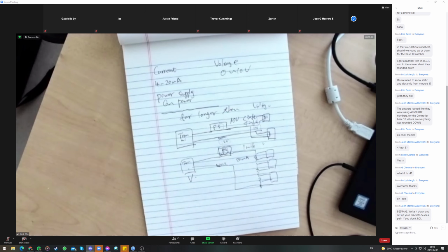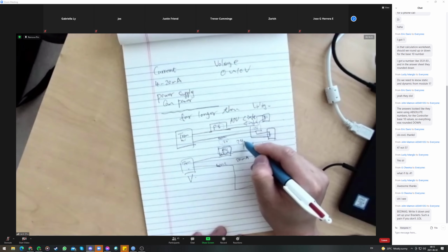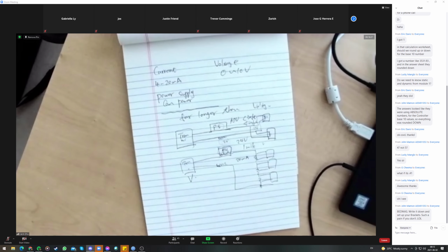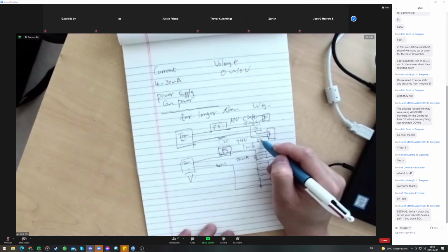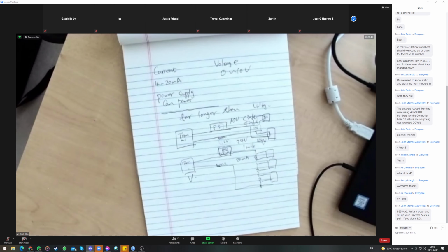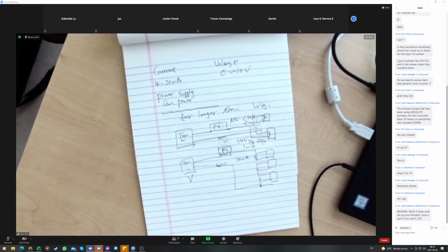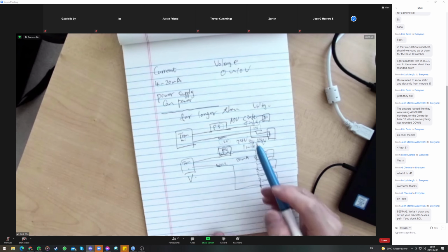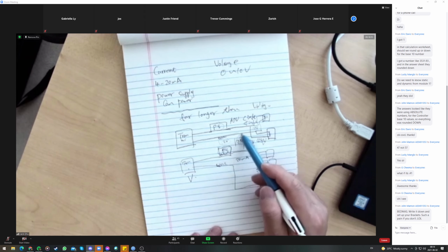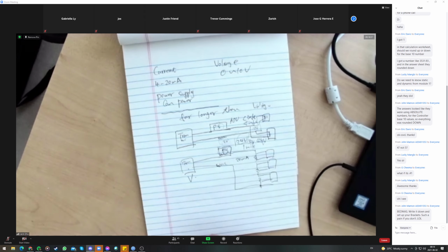Like yesterday, we calculated 24 volts power supply is very common in industrial control, right? Then the next one maybe 48 volts. But if you calculate, let's say, 32 volts as the required one, it's really hard to get a 32 volts power supply. So for that limitation, because 24 volts is so common, you have to be careful.